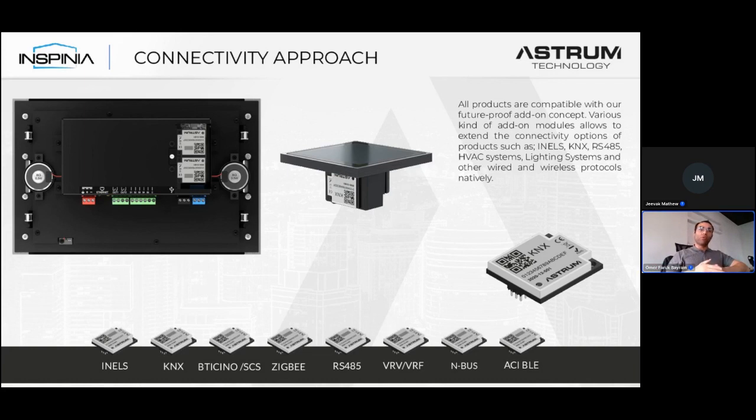These are all outdoor unit solutions. So our add-on VRF solution is for outdoor units. We are connecting to the outdoor unit directly. If there is more than one outdoor unit, no problem. We can connect outdoor unit to outdoor unit in parallel, so we can manage up to 64 indoor units.